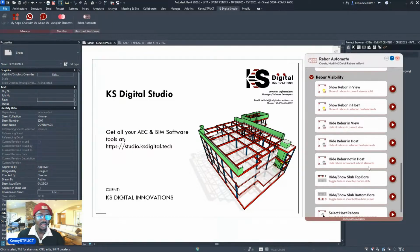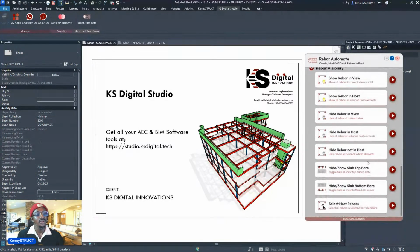In the sense that, okay, you have bars in your slab, and maybe your beam rebars are also showing in that view. And you want to hide every beam rebar, you can just select this tool and it hides, and select your slab, it hides every rebar that is not in that slab, that is not hosted to that slab.